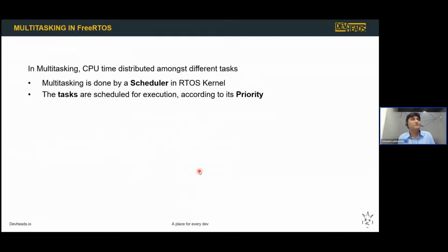We talked earlier about the difference between a task and a normal function, when I said a task is just a function with a dedicated stack, right? So here again, you have to notice that a task also has one more feature, which is a priority, which a normal function doesn't have, right? Unless you give it or unless you code it. So that's how multitasking is achieved.